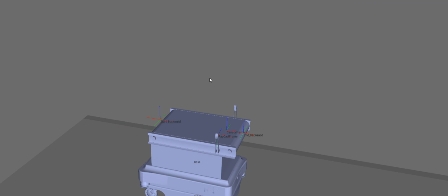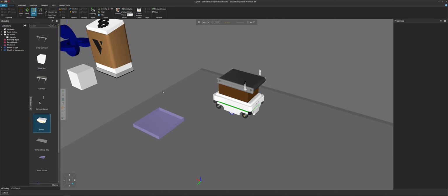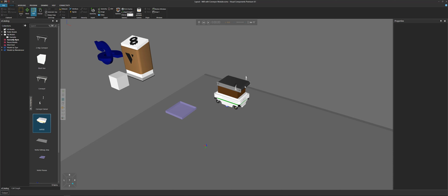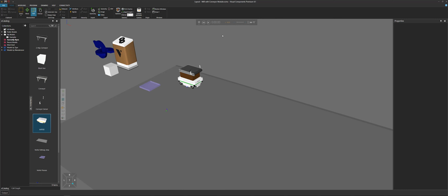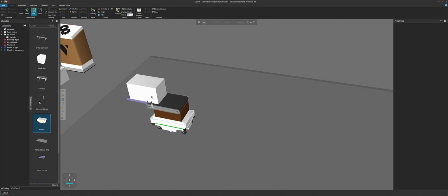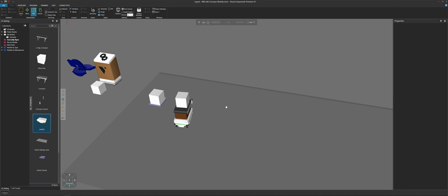Okay. So I hope by now you have a basic understanding of how you can use a Python script in the brains of your robot to create a custom type module, such as a lifting mechanism or a conveyor module, just by using simple code and arguments for what is needed to make that system work. So if we run this again, you can see the paths are turned on. We wait for feedback from the signal, and then the paths are turned off, and the robot knows it can start moving.